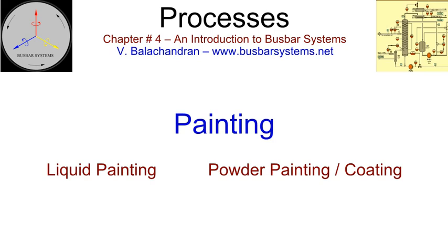Apart from the color, the finish, glossy, semi-glossy, or matte, does matter. A matte finish increases the area for heat dissipation and consequently is reflected as an increase in the relative emissivity. The enclosures of the busbar systems that are installed outdoors may also be exposed to corrosion, erosion, and UV radiation. UV radiations will weaken the bonds and result in the fading of the original shade. Consequently, painting materials that are resistant to the detrimental effect of the service conditions must be selected.